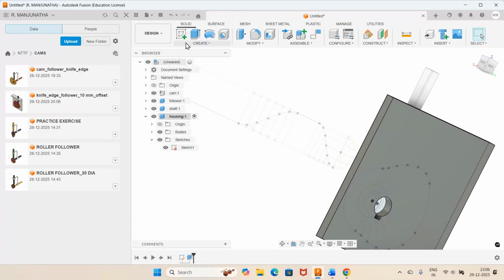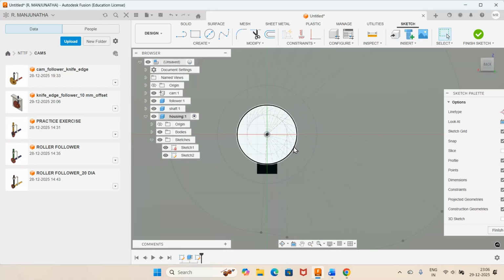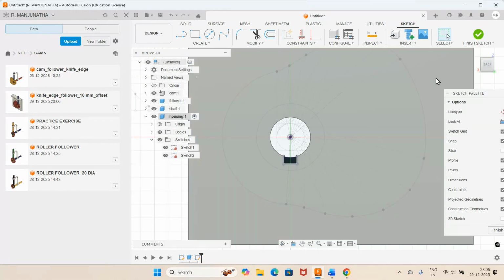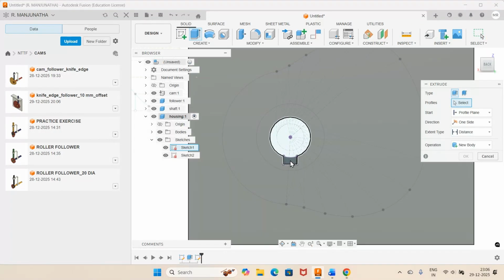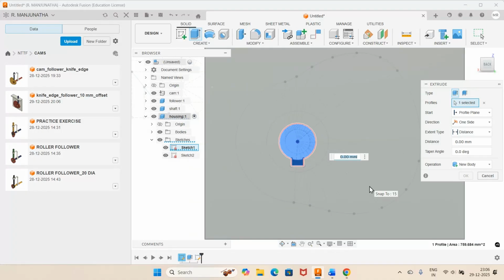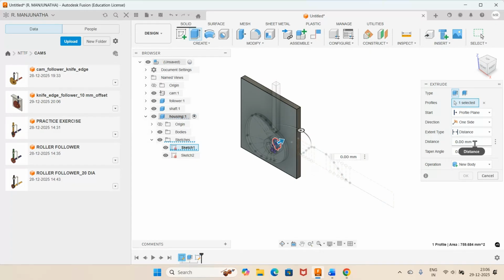So I'll just go to sketch, select this portion, and go to project. Can we include this portion? Let us see. Yes. Go to OK. Then I will go to finish sketch and I will go for extrusion. Select this profile and go to the distance. Go to 3D. Go to -15. Let us see how much we're going to get. I want join. Okay. And say OK.